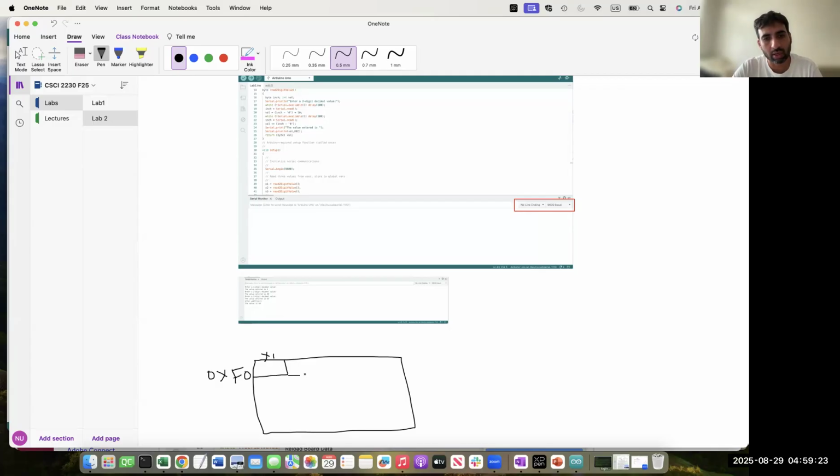So when you say .byte x1, 1 byte is reserved and it is given the name x1. Now when you say .byte x2 1, another byte is reserved and it is given the name x2. And when you say .byte x3 1, another byte is reserved and it is given the name x3, right? Since these bytes are reserved and named, you can address these memory locations by their name. Instead of specifying the address of those memory locations, you can just specify their name in your code, like x1, x2, and x3. So this is just like having variables in the C language, right?